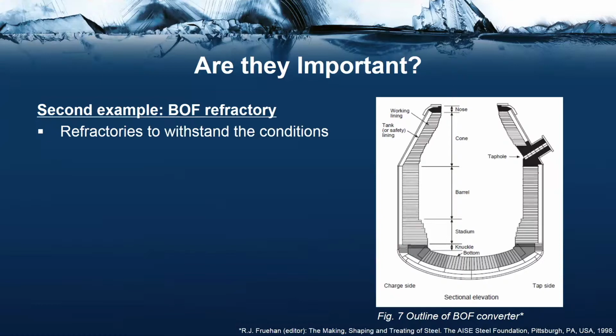Naturally, poor properties would mean more frequent relinings of the converter, which is accompanied by cost. A balance of properties such as hot strength, oxidation resistance, and slag resistance are necessary for good performance and long lining life. In this example, we'll consider the slag-resistant aspect in terms of slag design.